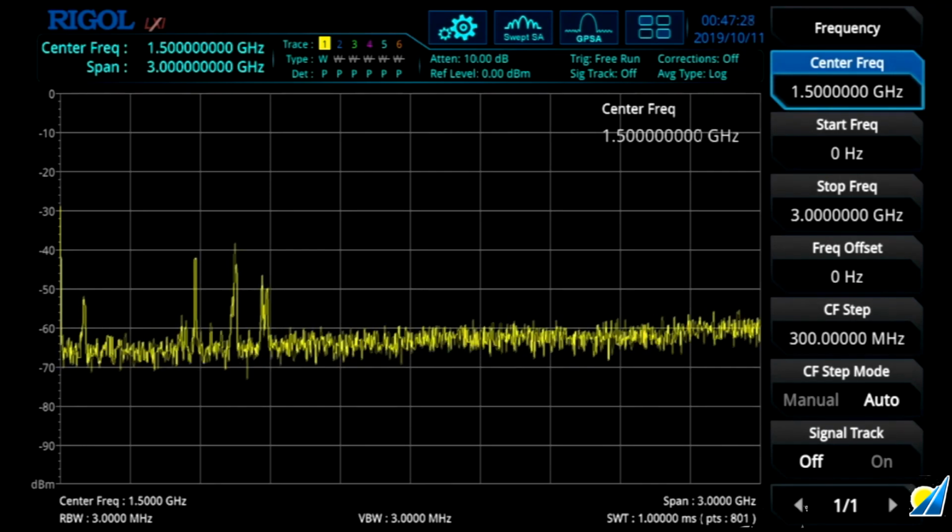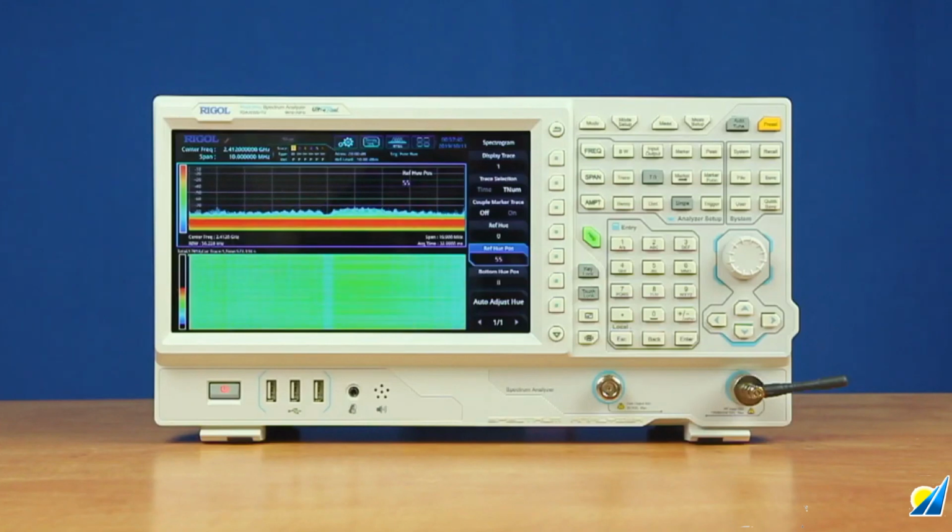We can also set the instrument into real-time spectrum analysis mode, which gives us the ability to see more complex and intermittent signals due to the real-time bandwidth and very low POI. With 10 MHz of real-time bandwidth, seamless capture, and a 9.3 microsecond 100% POI, verify and debug the complete transmitter operation, investigate unwanted signal components, and sources of interference.